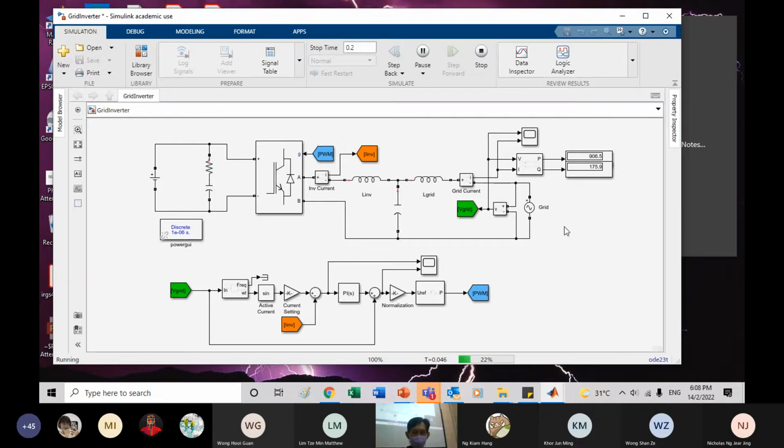So you will notice that 4 amp, 230 volts. So 900 over what, right? You can see that the output is 900. Okay, 0.6. And there is a bit of reactive power here. You see, if it's 100% real power, you will get 960. But there is some reactive power here. That's why you get around 900 watts.